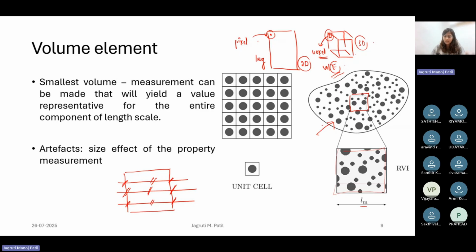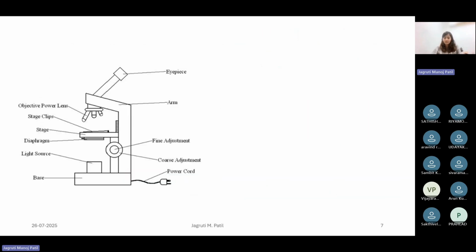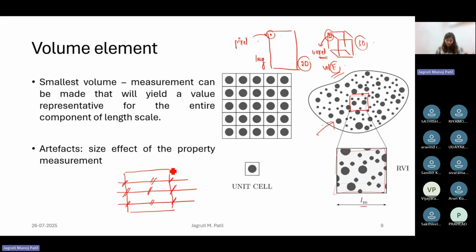Okay. So you might be able to say something about the structure of your material, but the structure differs from side to side. It differs from this particular length to this particular length. So be careful about what particular feature you're trying to image, because images might differ depending on which surface you look at. From this surface, you have something out here, something in here, something here, and something here. It's always better to image a particular surface in a way that you have a similar layer height, meaning a similar depth.